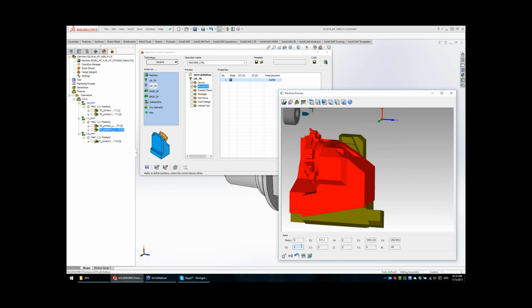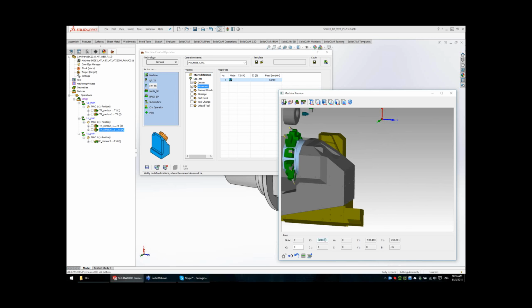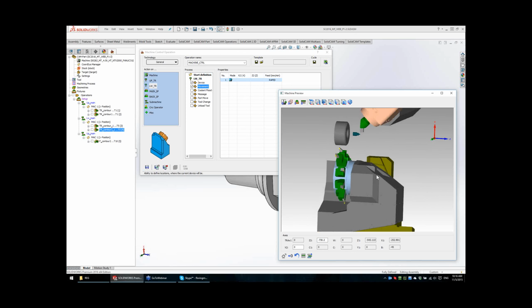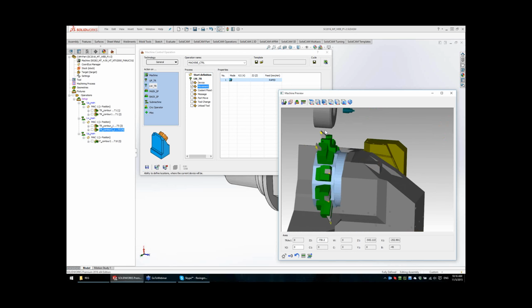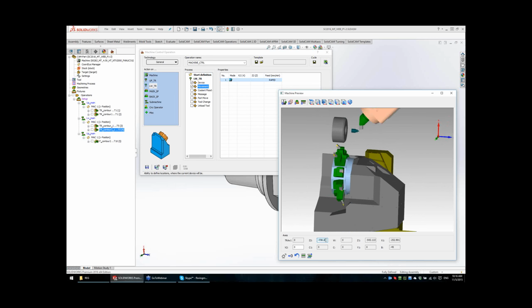Oh, that's the limit. Great. So I'm on 0, and now I will move with the mouse wheel in Z direction. That's enough here, this position. It's safe for me. The tool have no collision with the spindle. Everything is okay. Dimension is not important to be something precise, 750 or any other number. I just want to bring the turret to a safe position.